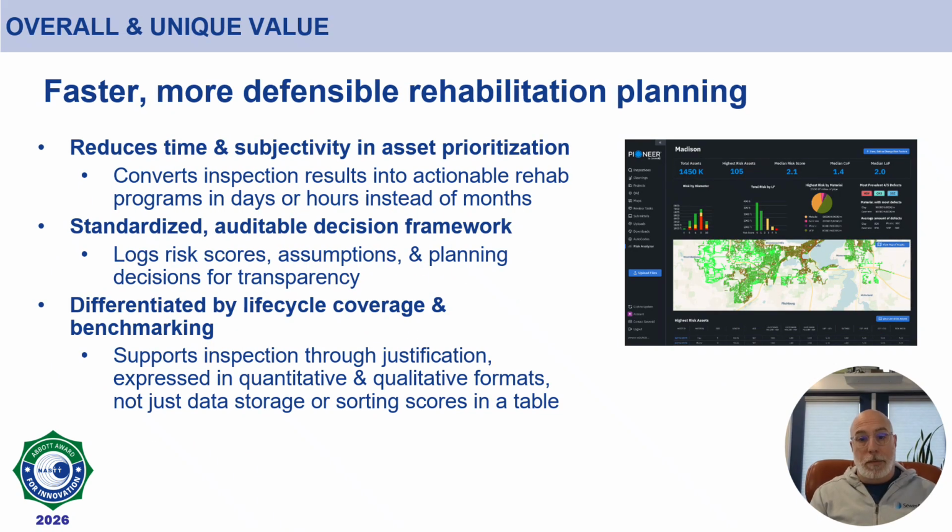From a practical standpoint, the overall value is reduction of time and subjectivity in capital planning. What traditionally required months of spreadsheet modeling can be accomplished in a single session. Assets can be filtered geographically or by condition class. High-risk segments can be grouped into work packages by basin, material, or rehabilitation method. And estimated construction costs are generated using structured decision logic and localized, customizable cost references, allowing utilities to move directly from inspection to budget development.